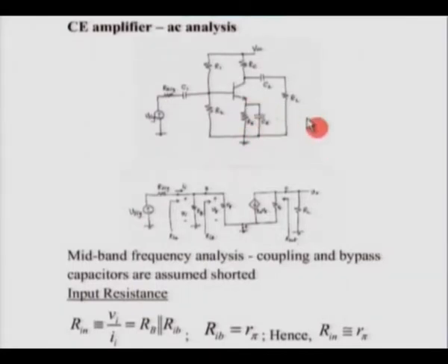Now, we can have two types of common emitter amplifier depending on whether we have a capacitor connected between emitter and ground or not. In the first case, the most common case, we would have a capacitor CE connected between emitter and ground. In today's lecture, we will not look at the details of the low frequency response. When we do the analysis, we would see that the value of CE would be much higher compared to C1 and C2. Typically CE would be of the order of 50 to 100 microfarad. Here again the polarity is quite straightforward. Towards the emitter you would have positive polarity for the electrolytic capacitor and the ground negative polarity.